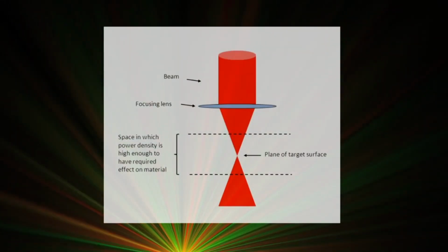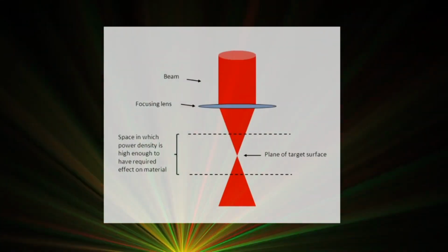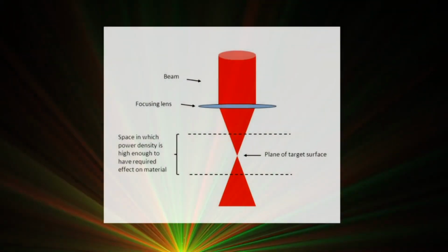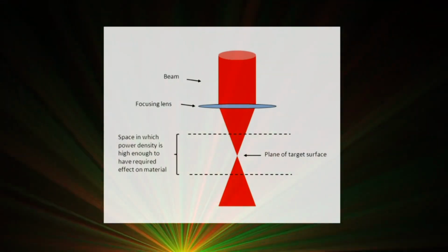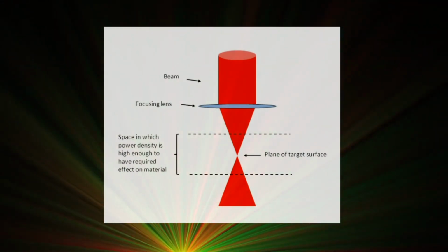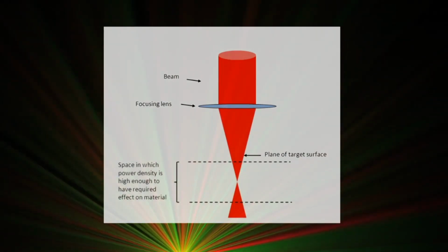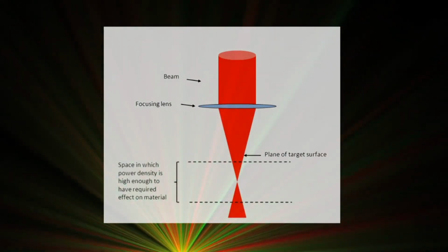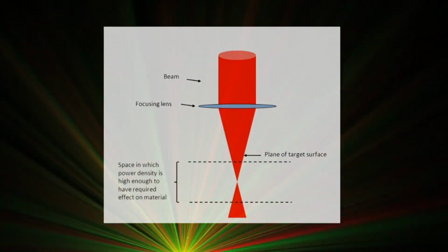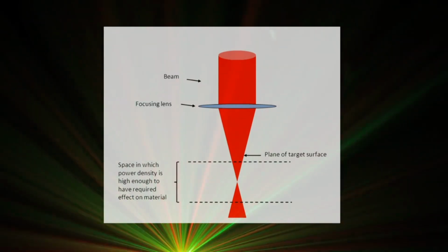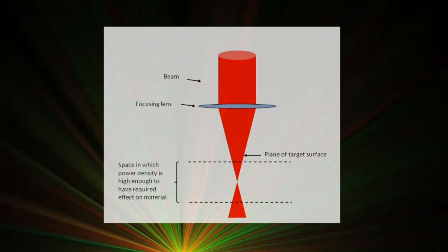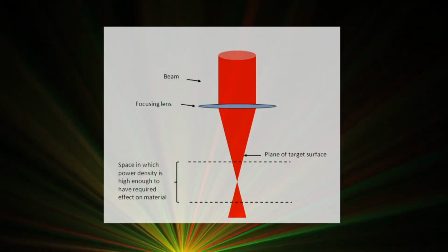With ever-increasing power levels in today's industrial laser beams, heating effects on the laser's optical components, such as a focusing lens or a window, can cause a shift in the focal point location, moving it closer or farther away. It's easy to see how such a focus shift can critically change what the process is doing and where it's doing it. To ensure a consistent process over time, the relevant laser parameters must be measured as a function of time.